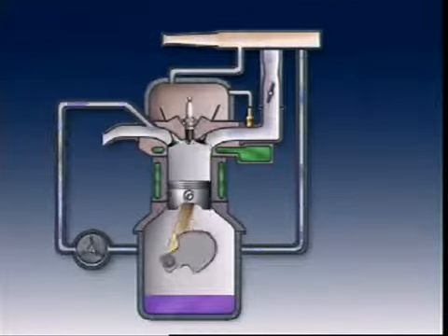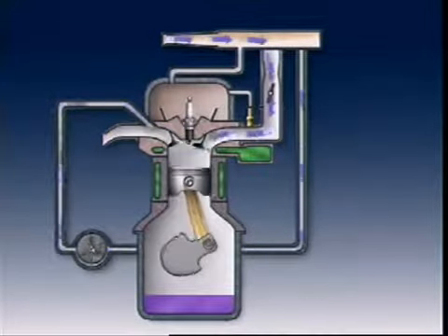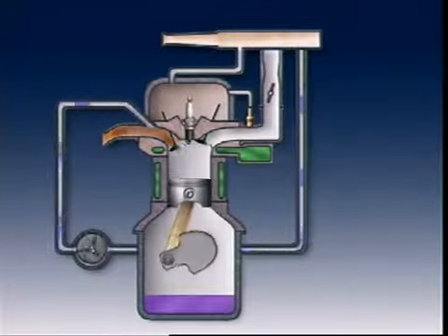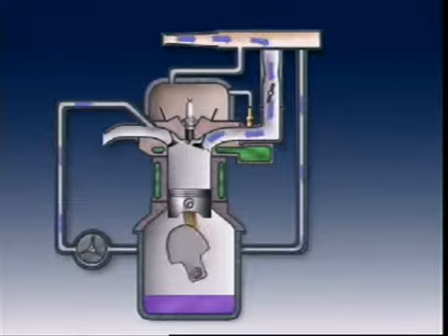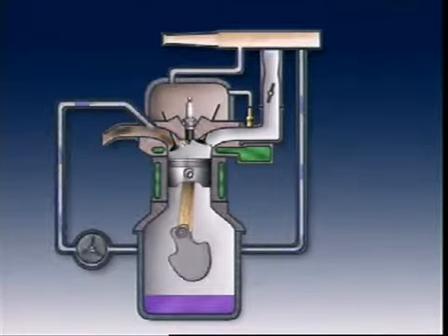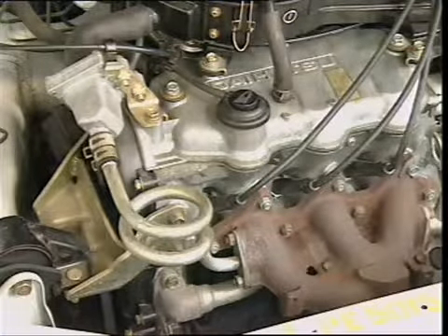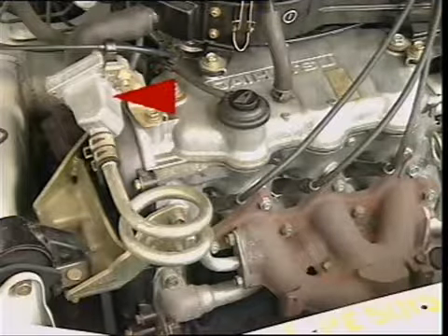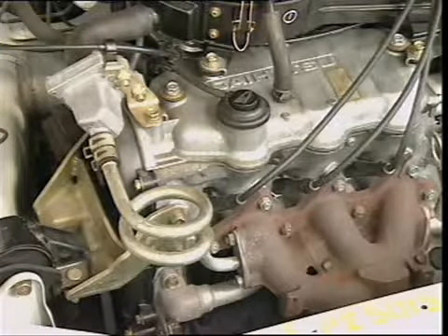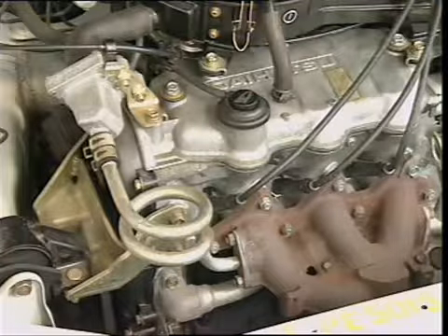If the exhaust gas is hot enough, combustion of remaining hydrocarbons and carbon monoxide can be completed by adding extra air to them at the exhaust port or manifold. This afterburning produces water and carbon dioxide, which are then exhausted to the atmosphere. The pulse air method uses the pulsations of the exhaust gas to open and close a reed valve. It admits air into the exhaust manifold in short bursts. Air drawn from the air filter enters the exhaust manifold.